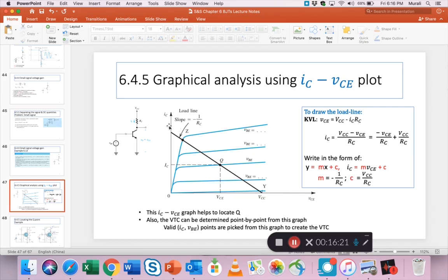That relationship and the combination of the load line together helps you pick a number of points. So for example, this point is where a VBE line intersects the load line. Similarly, this point, this point, this point. So right here we see 4 points, and maybe this lower one 5 points, that give you a certain combination of this VCE and this IC.